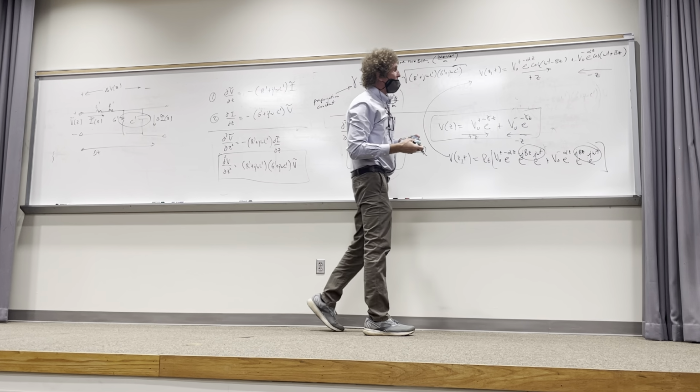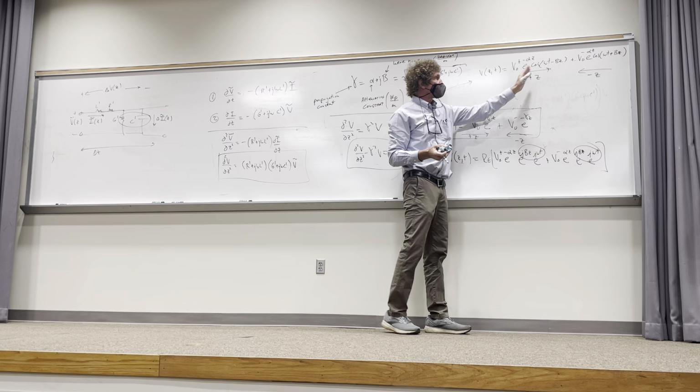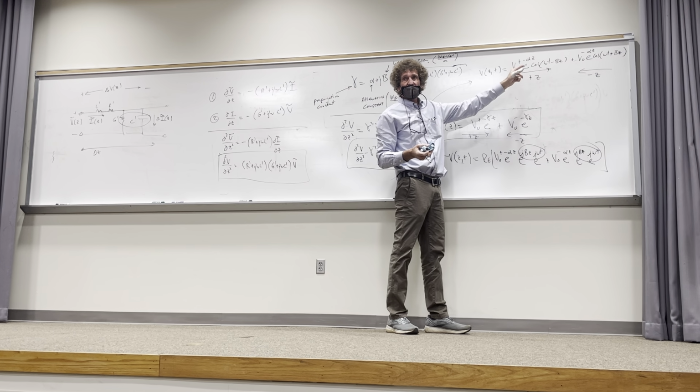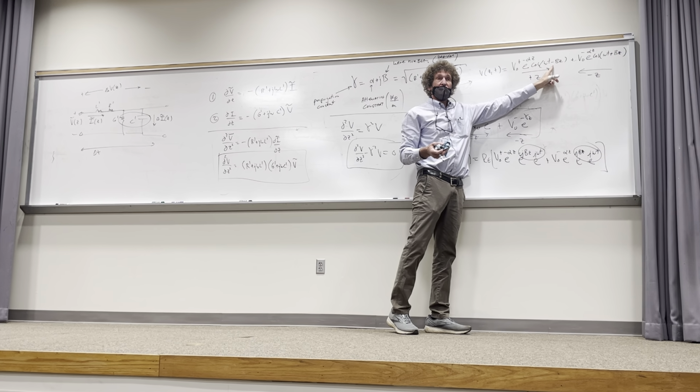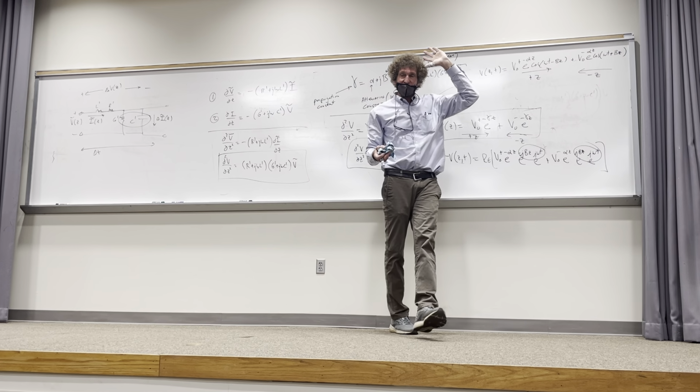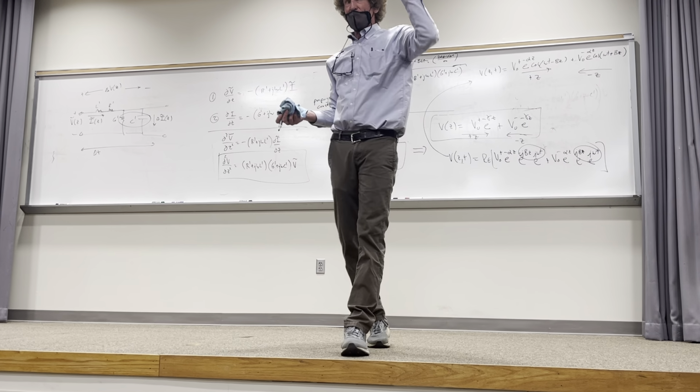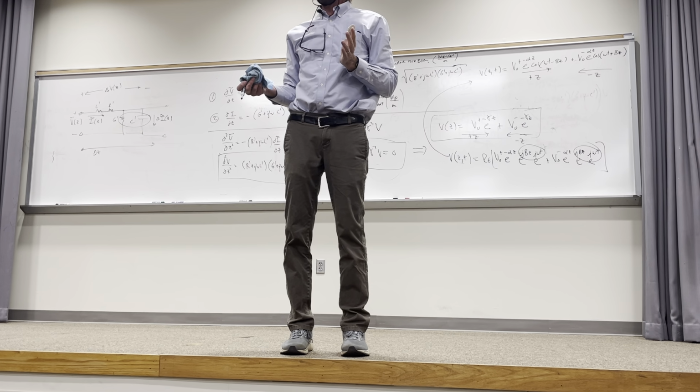Now, this waveform is defined for all space, isn't it? If I have a cosine of omega t minus beta z, it's everywhere. You pick a value of z or t, something exists. It'll have nulls, it'll have values of 0, but it exists everywhere. So how do you prove that it's actually propagating that way? Well, what you do is take a look at the phase velocity. Remember phase velocity? How many remember how to get the phase velocity? Anybody?